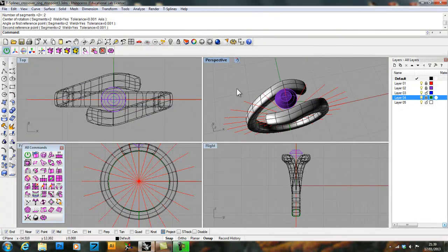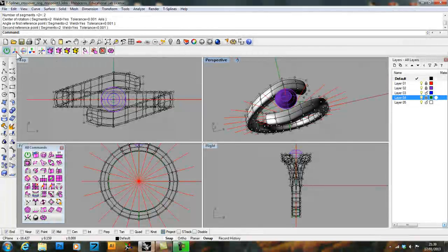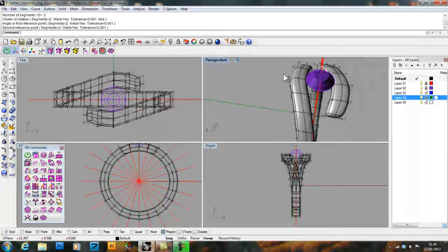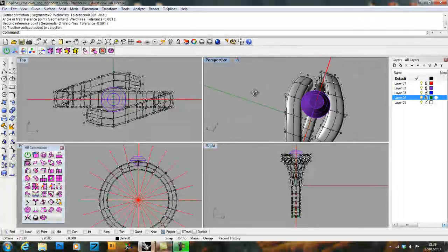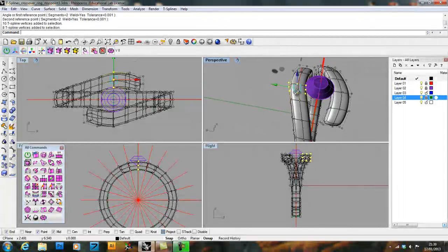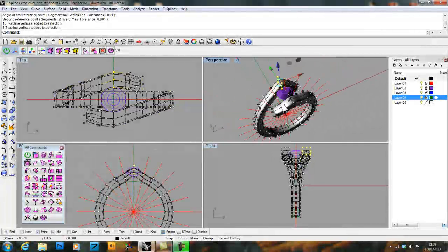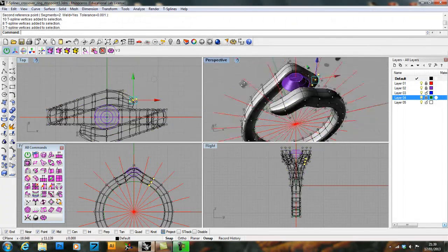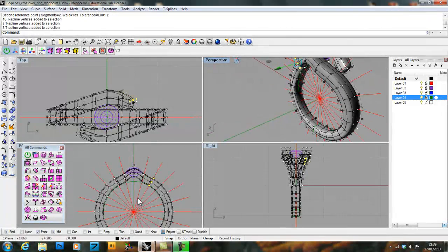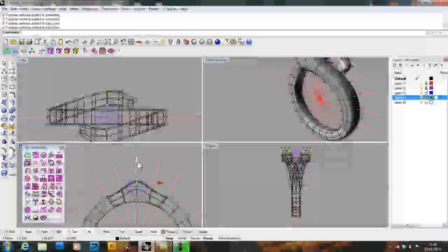Now, any change that I make to the shape, such as if I go back here to the vertex control, and I grab some of these points, will happen to, let's grab some better points than that here. Let's just go from this view here. There we are. Now I can grab them, and one side will move with the other. So I can grab these points here, and I can move them down. And so from here, it's only a matter of picking the points you want to move, manipulating them, until we get exactly the shape we want.